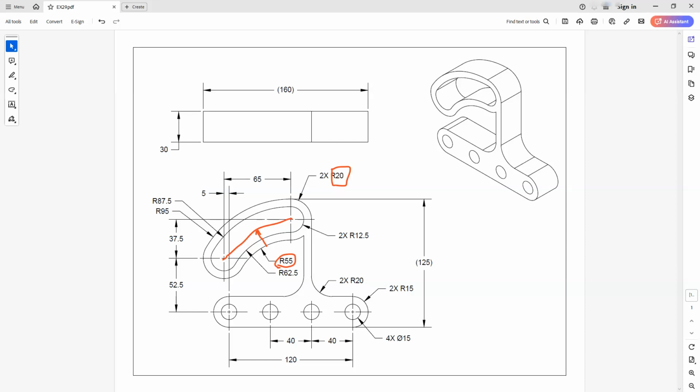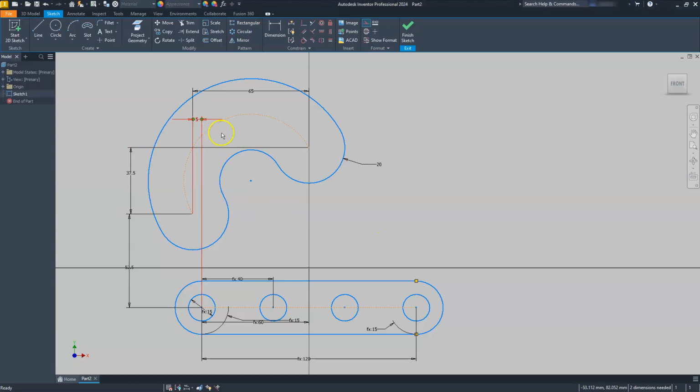It starts at 55, then it goes to 62.5, which is located at this one. And then on the other side here, we're getting 87, and we're getting 95. So that just tells me that I need to add this number to this one. So I'll get 55 plus 20. In that case, the number that I'm going to need for that radius should be sitting at 75, right? All right, so let's jump back to that, and then we're going to put our radius at 75. Okay, so let's put a dimension on this and make it 75. And there we go.